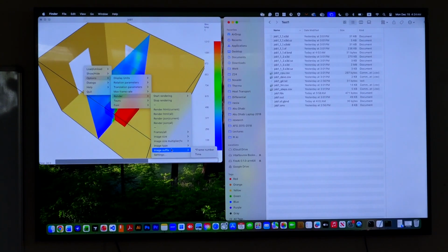So if you remember in the code we gave a command ampersand DUMP with NFRAMES is equal to 60, right? So basically we told FDS to create the files at every second, right? Because your simulation time was 60 seconds, right? So it is going to generate maybe around 60 PNG files, okay? Alright, so how do you want to save the files? Using time or a frame number?